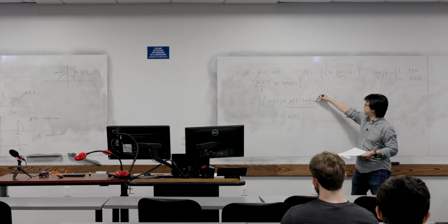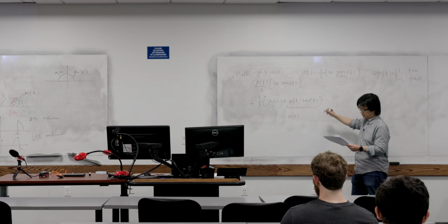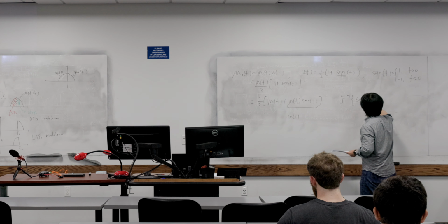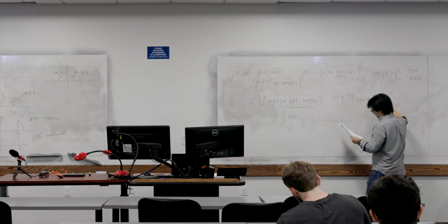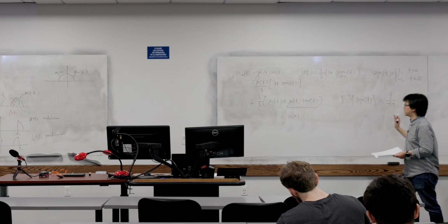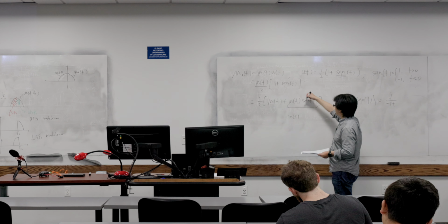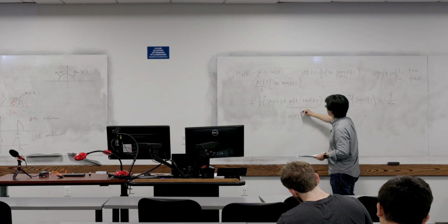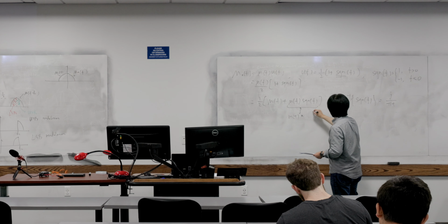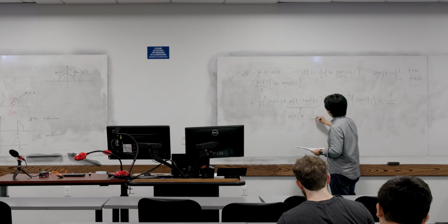And what is the inverse Fourier transform of this guy? Yeah, let me tell you. The inverse Fourier transform of this guy is j over pi t. So basically, in the frequency domain it's a multiplication, then in the time domain it equals m(t) convolved with j over pi t.